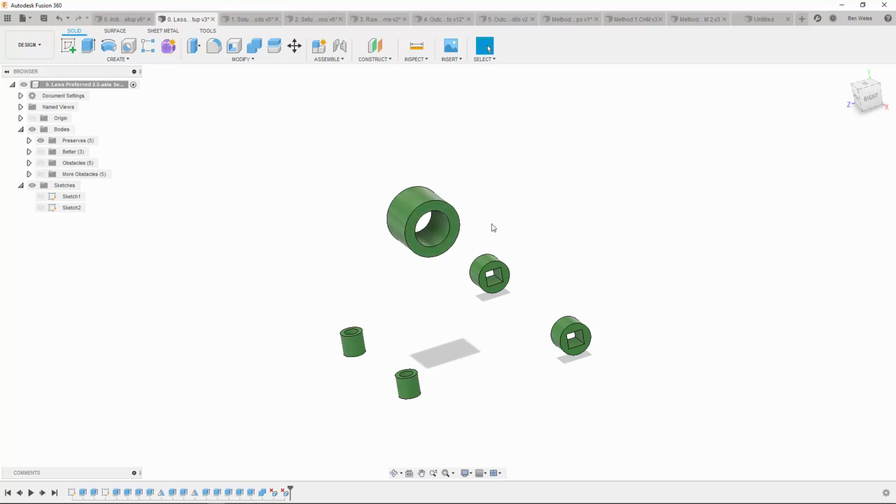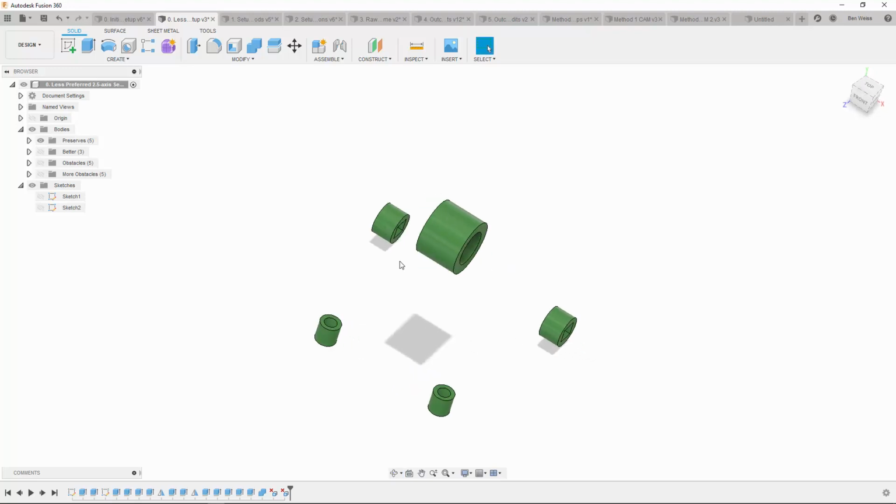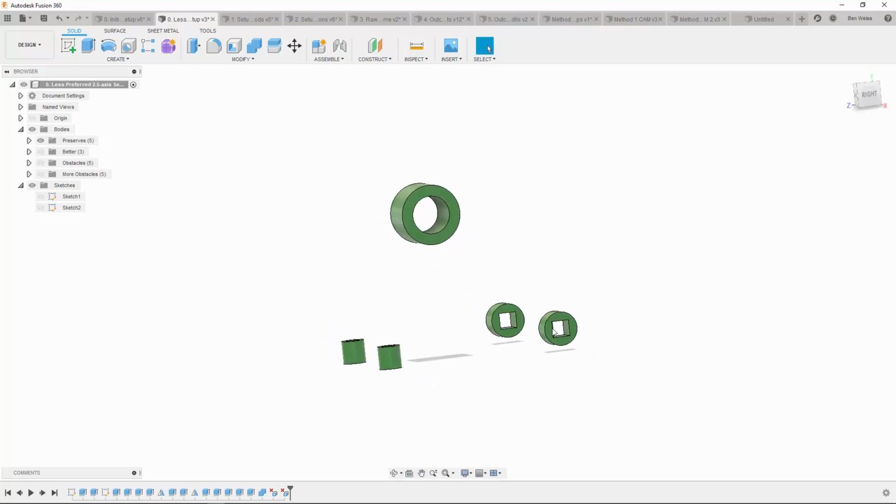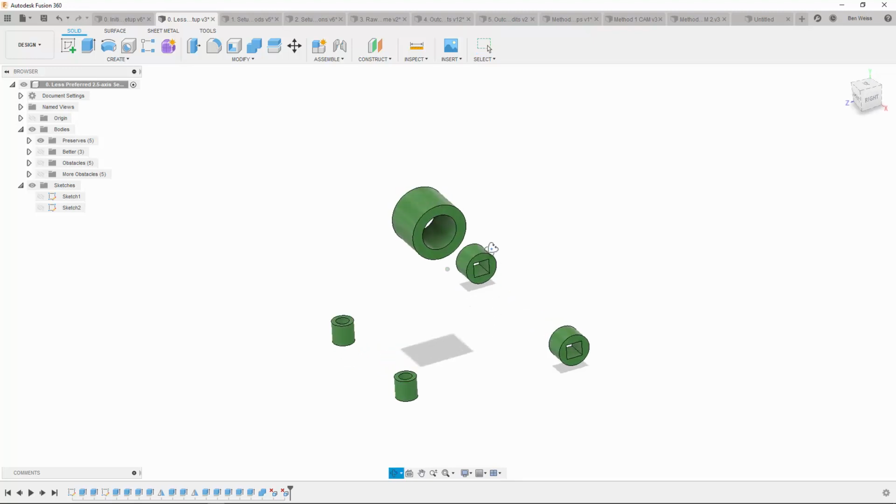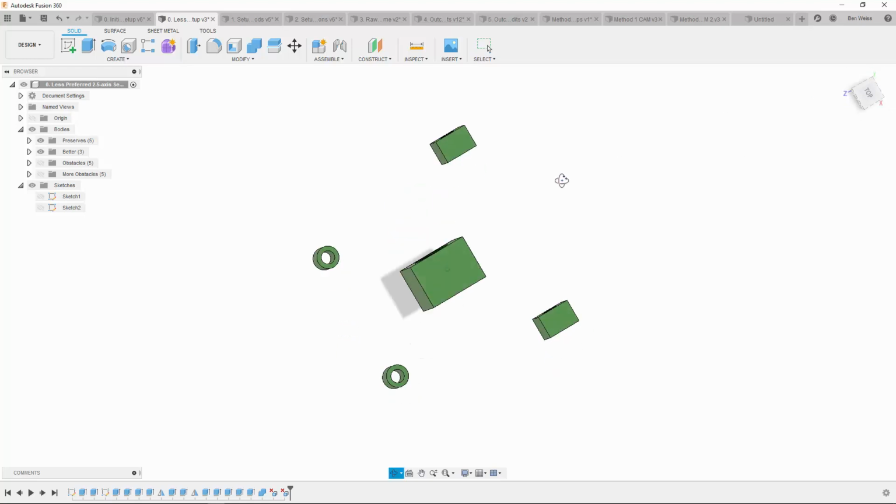In addition, the preserved geometries themselves are difficult to machine. We'd have to do this with at least 2 setups, and I don't know about you, but I have a hard time machining square holes any day, regardless of how many setups I have. So we can improve this design for 2.5-axis by doing the following. First, let's rethink our setups. So I've decided that I'm going to approach this from the Y direction. So we'll cut it from the top like this.